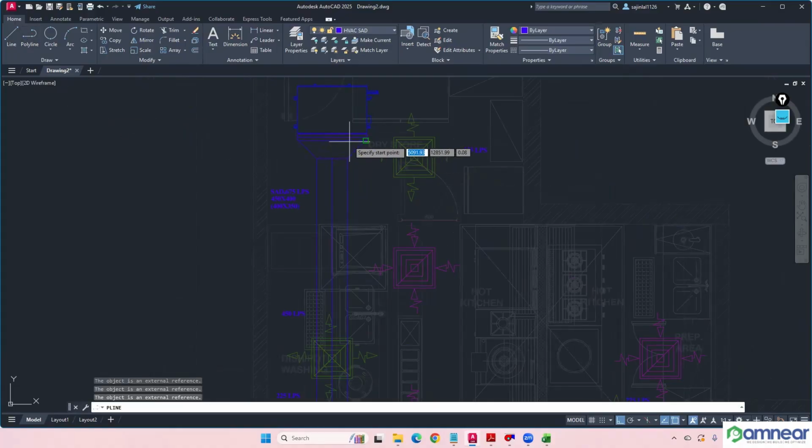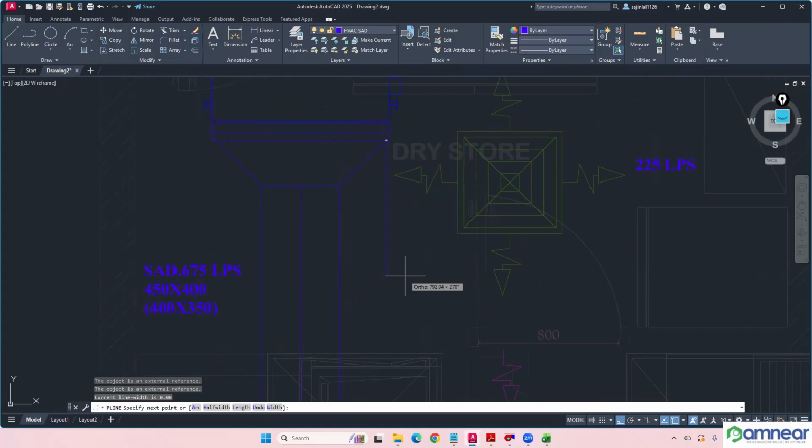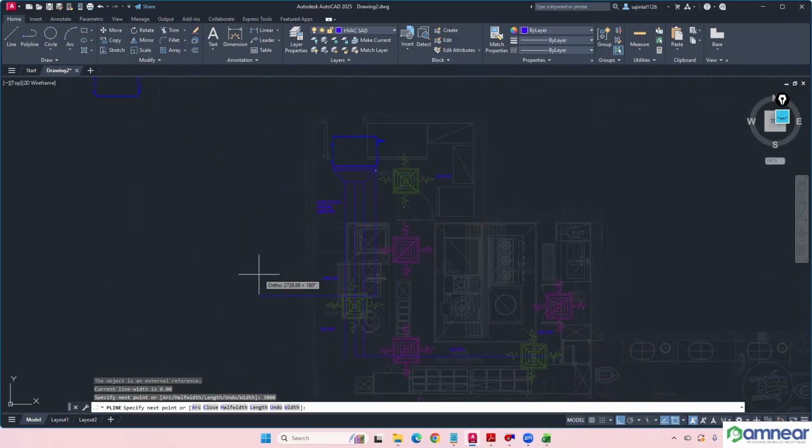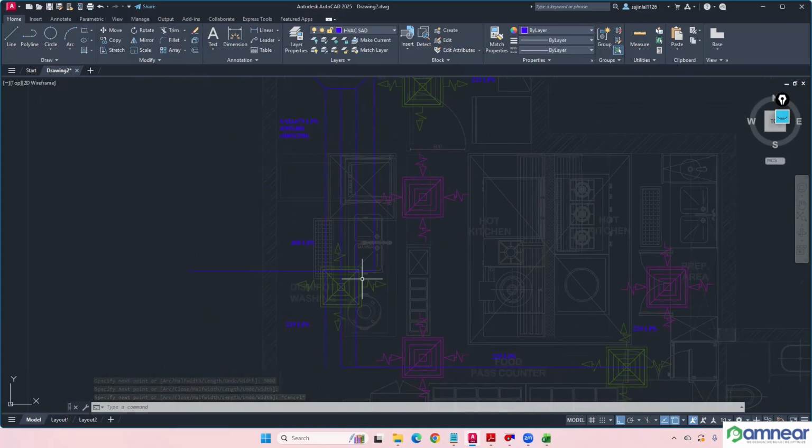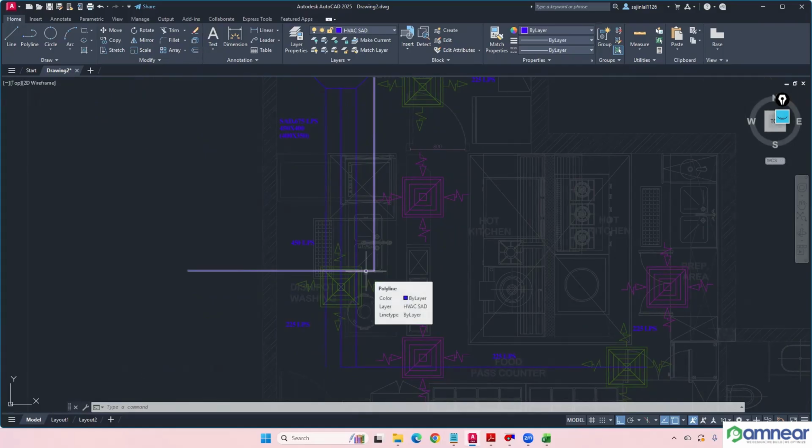So 3 meter will come somewhere up to here. I need to provide acoustic lining. So up to here, I will not be decreasing the duct dimension. Anyhow, until here, it is not practically possible. Otherwise, in this branch also, I need to consider the acoustic lining.